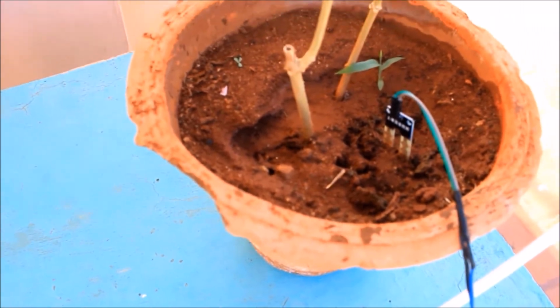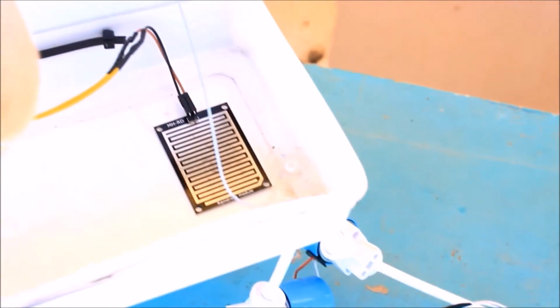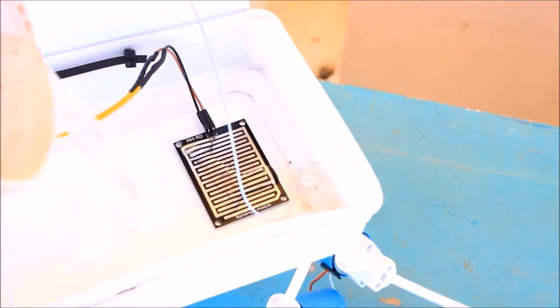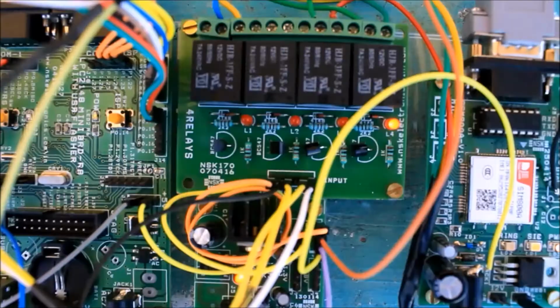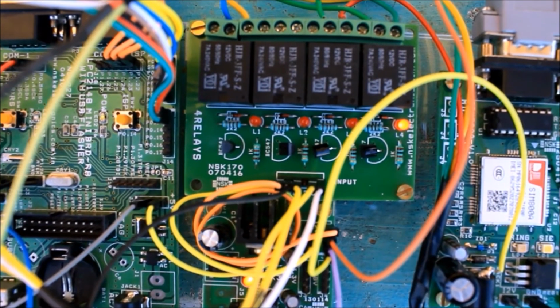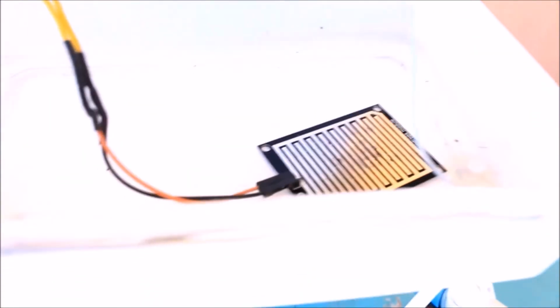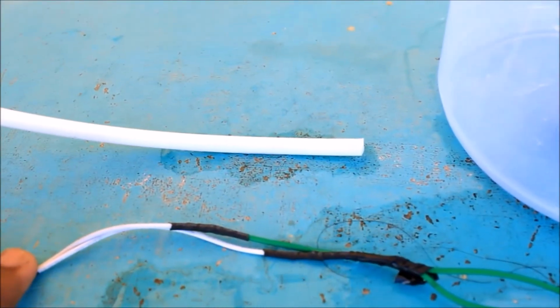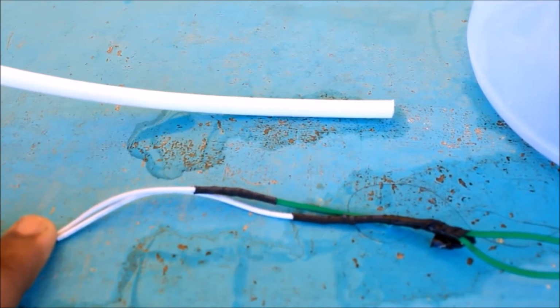This project has two parts, that is the raining process and the soil moisture process. In the raining process, the sensor placed on the terrace is energized while raining and gives the signal to the LPC2148 microcontroller, which triggers solenoid 1 for a few seconds and turns it off, and then turns on solenoid 2, which will fill the rainwater into the tank. Here you are seeing solenoid 2 is energized.